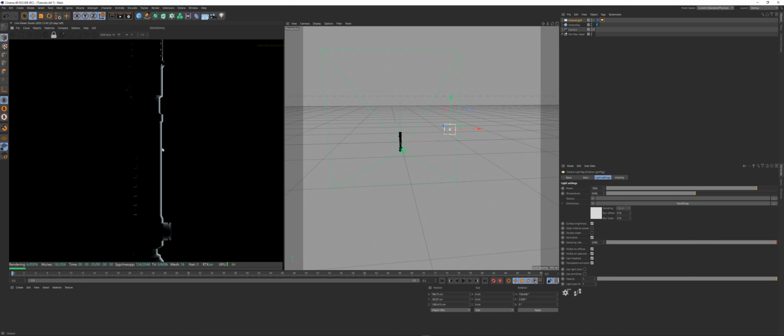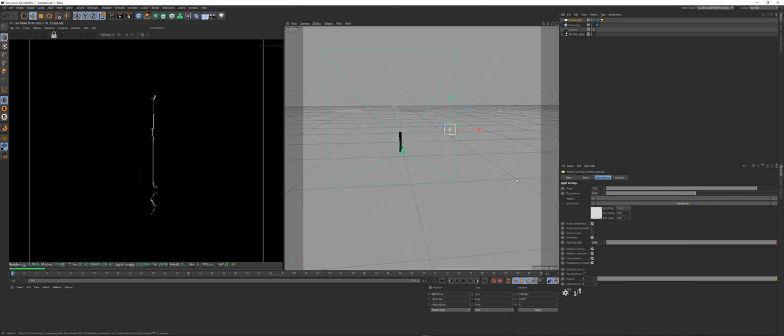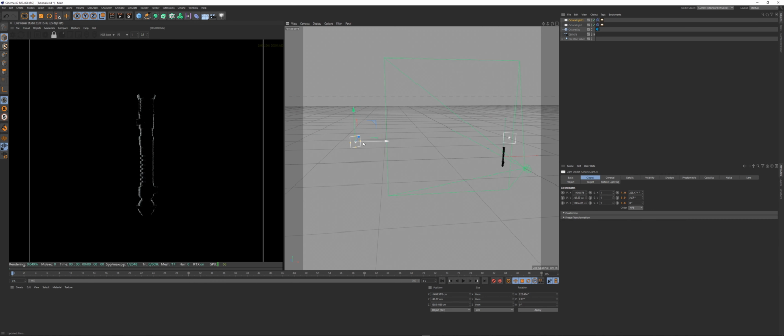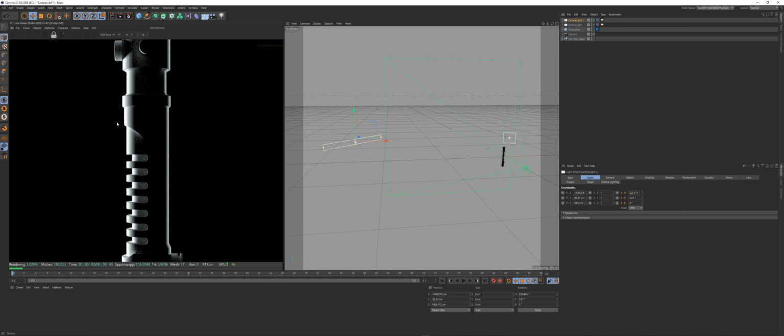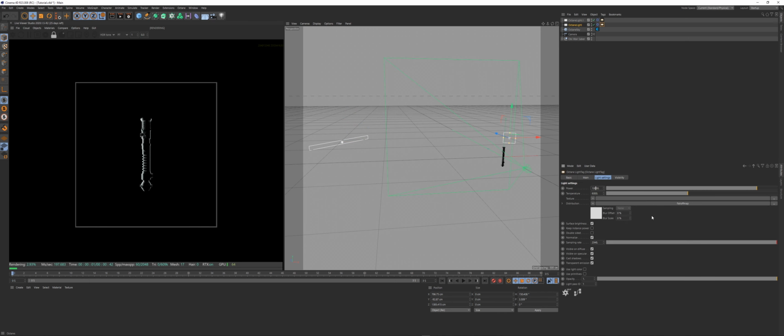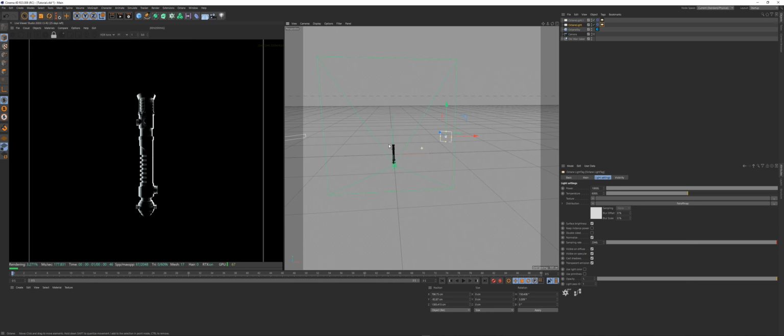You can see now we've got a nice little room light going there. I'm going to try and push that off of the blue tone that it's in by default. Maybe keep it at 6000. And then, holding control, I'm just going to drag the light over, create a second one. I'm going to make this one a little bit wider so it wraps around the cylinder that is the lightsaber. And then I think I'm actually going to make this one 10,000 so it blows out this side a bit. Press W to get back on the object axis. Just push that back.